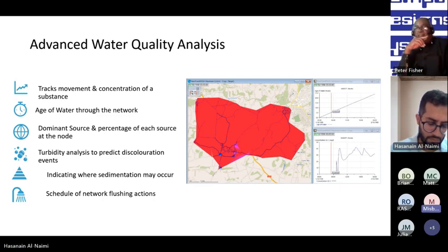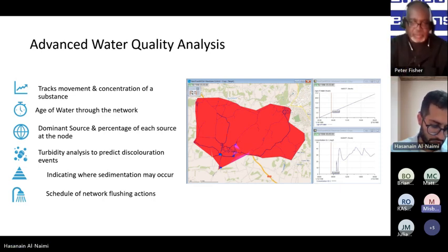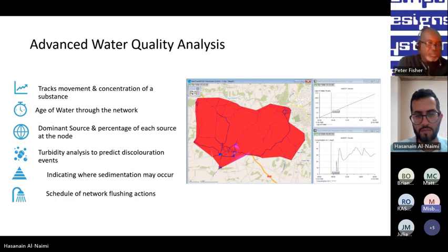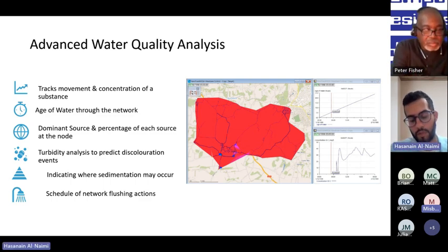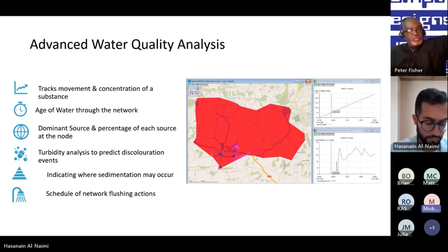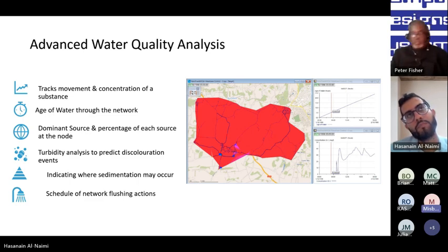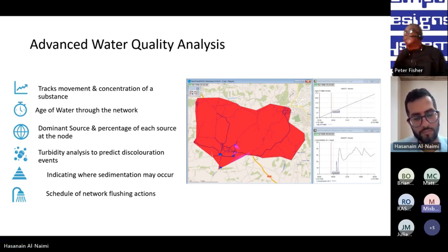When you do calibration, it gives you an insight into what the roughness friction factor of the pipe has become after so many years of usage. If you had data to do the calibration, you could put that data in the software, and it can simulate and come up with a range of roughness coefficients based on the simulation runs.